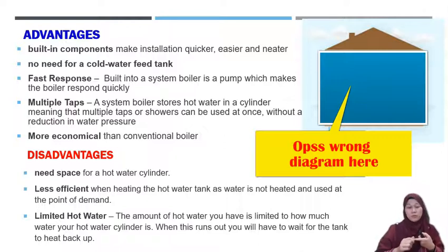Multiple taps you can use simultaneously, the hot water from the bathroom and from the kitchen at the same time, because they have the hot water cylinder to store the hot water. More economical than a conventional boiler. That's the keyword: more economical than a conventional boiler, because the system is simpler compared to conventional.